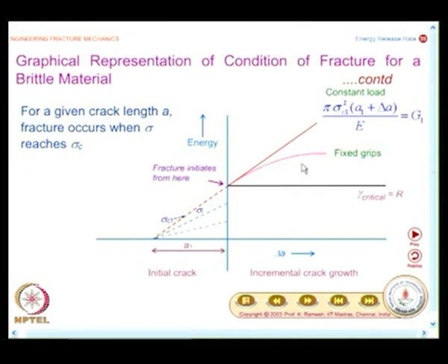Suppose I have more energy than what is required for the formation of crack surfaces, this would propel the crack at increasing velocities. So, what would happen is the crack would initiate and it would acquire a velocity. People have studied all that using photoelastic experiments.